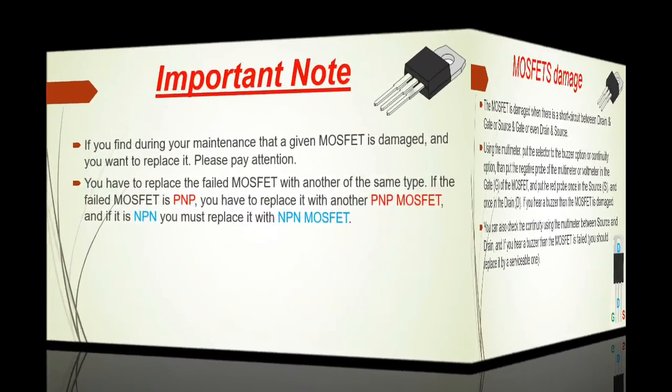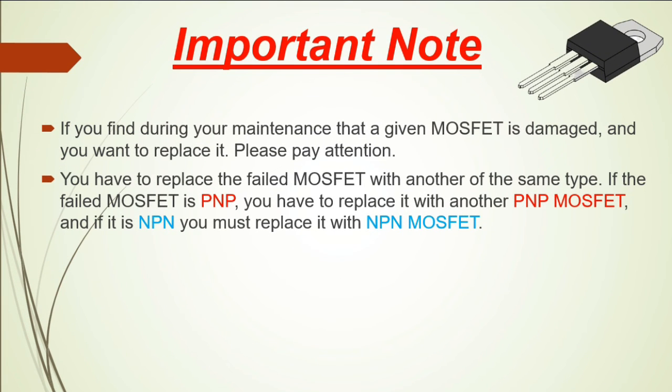To say an important note for any computer technician or electronic technician, please pay attention to these notes, okay? If you find during your maintenance that a given MOSFET is damaged and you want to replace it, please pay attention. You have to replace the failed MOSFET with another of the same type, okay?